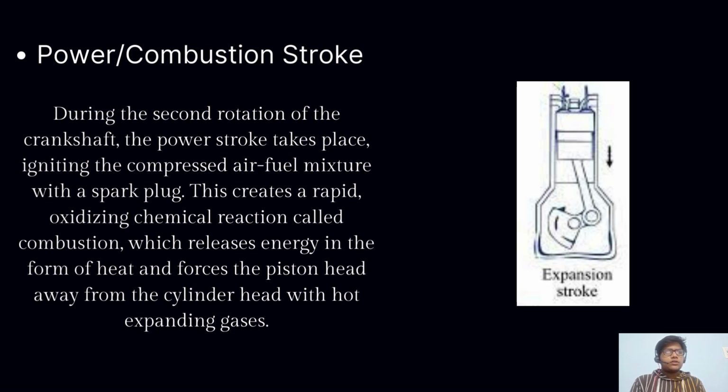The power stroke occurs when the compressed air fuel mixture is ignited with the help of the spark plug. Ignition or combustion is a rapid oxidizing chemical reaction in which a fuel is chemically combined with oxygen in the atmosphere and releases energy in the form of heat. The hot expanding gases force the piston head away from the cylinder head.